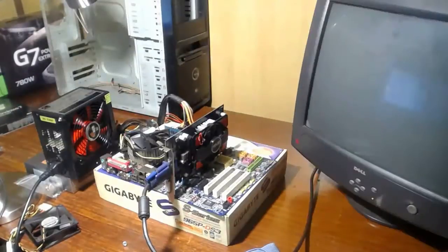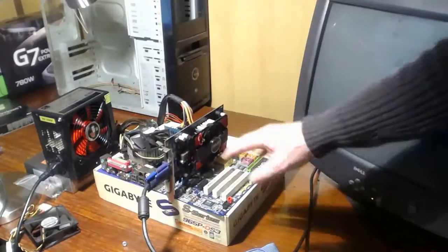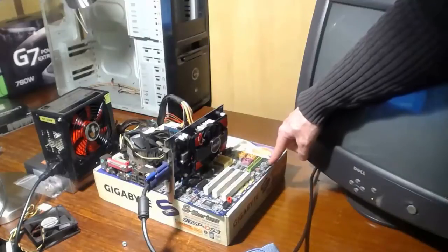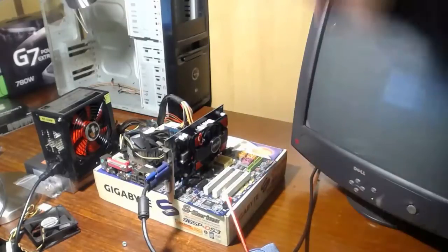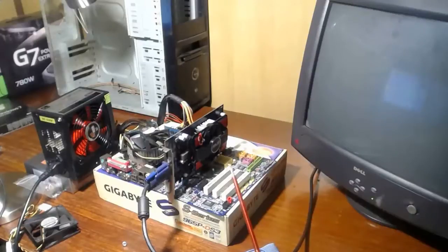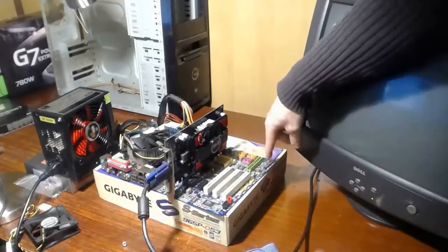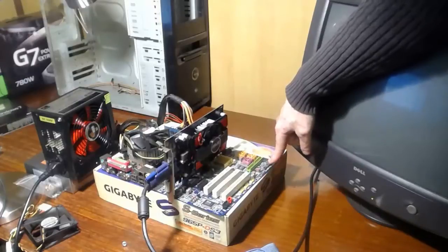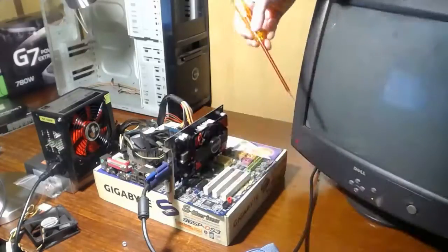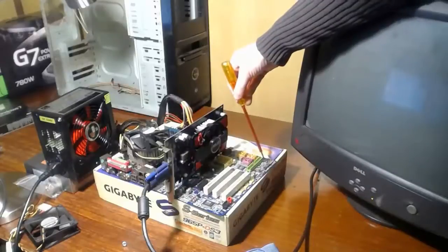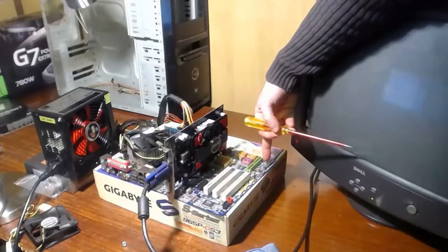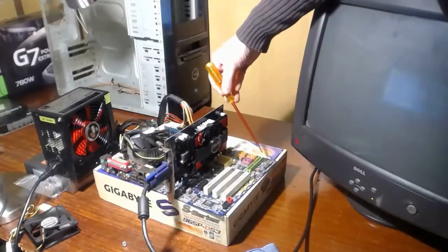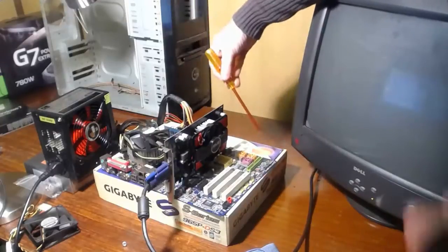Now, in order to turn the system on, we have to turn on the power button, and the best way to do that is to get a flathead screwdriver and touch the power switch on the front panel connections here. Just tip it once. I know it's the little red connection here, the 2 pins in the red connection, so I'm just going to touch the 2 of those, and then the system should power up and we should see a post here on the screen.